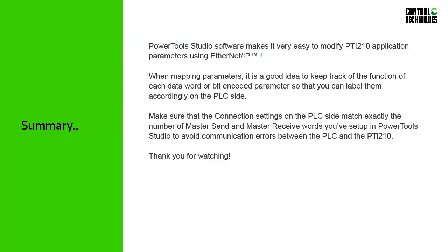PowerTools Studio software makes it very easy to modify PTi210 application parameters using Ethernet IP. When mapping parameters, it is a good idea to keep track of the function of each data word or bit encoded parameter so that you can label them accordingly on the PLC side. Make sure that the connection settings on the PLC side match exactly the number of master send and master receive words you've set up in PowerTools Studio to avoid communication errors between the PLC and the PTi210.